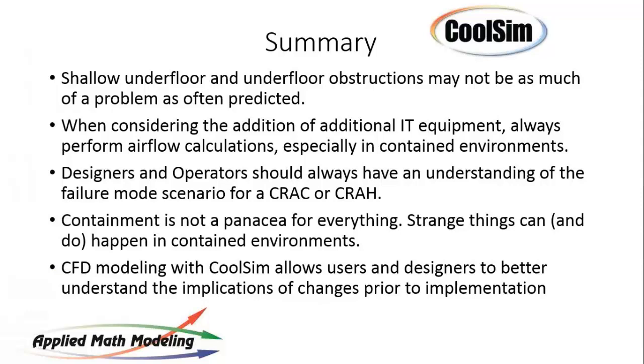One of the things about containment is that if it's too tight, and you have a failure on one side or the other, things will go up really fast. The beauty of a convective room, a room with no containment at all, just natural convection, is that if something fails, the racks will recirculate the air on themselves for a period of time and give you a little bit of room to recover.